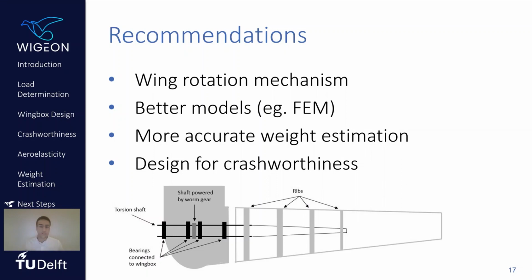Also, we may choose to explore other weight estimation methods than the ones I showed you before in order to get a more precise estimate for the subcomponent weight. Lastly, while we did take crashworthiness into consideration for the whole aircraft, the accelerations endured by each structural component and their corresponding energy absorption is yet to be determined.